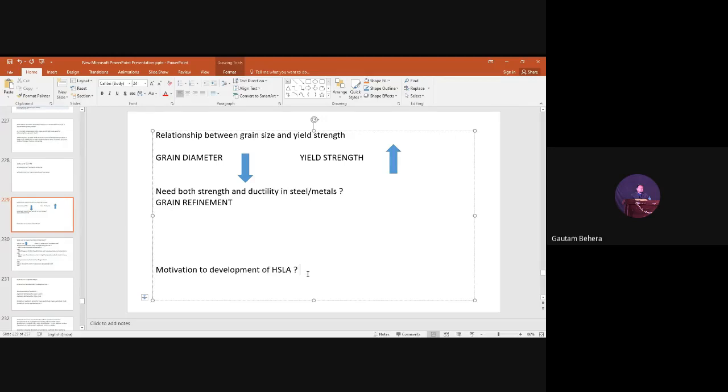Anyway, with high strength low alloy steels, you understand that the weight will be minimum but strength will be very high, right? These high strength low alloy steels contain a very low amount of carbon, at maximum up to 0.25, not 0.02, 0.25. The minimum amount of carbon. Manganese concentration will be up to 2%, but the other alloying elements which provide very high strength are vanadium, niobium, titanium. So these are the major alloying elements: vanadium, niobium, titanium.